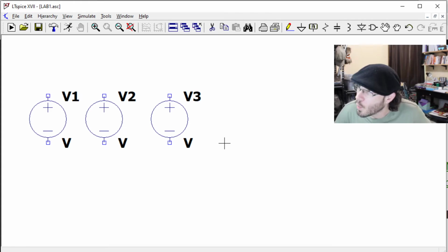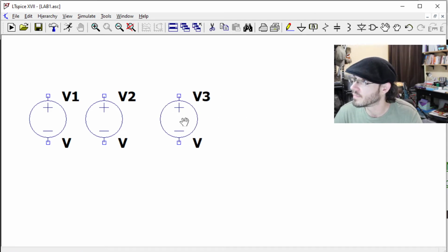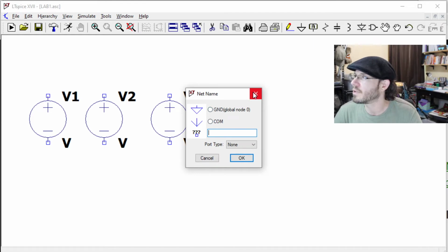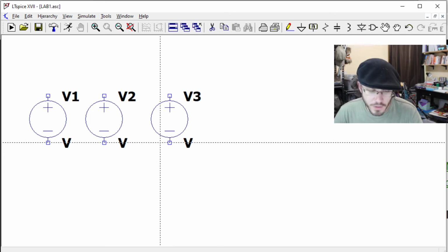Okay, a quicker way to get to the delete tool is if you have function keys that work at the top of your keyboard, you can hit F5. F5 takes me to the scissor tool. F6 takes me to the copy tool. F7 takes me to the move tool. F8 gives me a hand closed tool. I'll be honest, I'm not quite sure what that does. F4 comes up with a labeling tool. F3 comes up with a wiring tool. You see, all of my tools are accessible across the function keys.